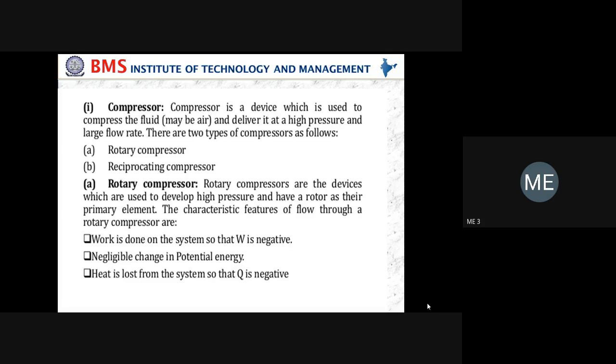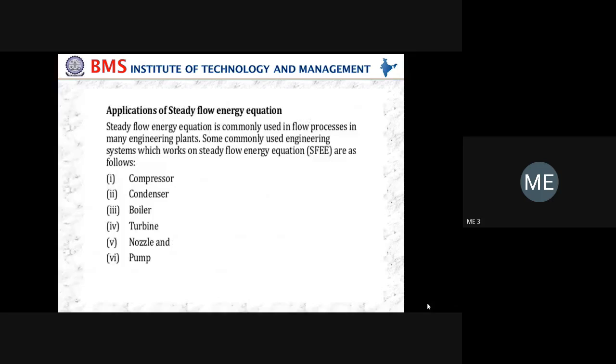Okay. That's all. Now I'm doing the steady flow energy equation. Steady state means the thermodynamic properties are invariant with respect to time. Remember steady flow. We have a separate subject called heat and mass transfer in sixth semester, and a heat transfer lab also. You are not going to start your experiment immediately, because once you switch on the motor, it will not be in the steady state. You have to wait for half an hour or 45 minutes, so that it attains the steady state. Then only we start the experimentation.